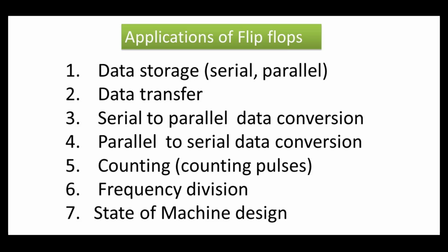The fifth application is counting pulses or counting binary numbers like 0 to 10, 0 to 9, or 9 to 0, or 0 to 100, up counting or down counting. In counting, we are going to use the flip-flops in asynchronous and synchronous mode. That means we are going to design 2 types of counting circuits. One is the asynchronous counting circuit, the second is the synchronous counting circuit. And later we are going to see how frequency division takes place.